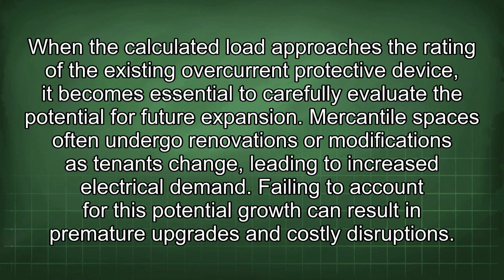When the calculated load approaches the rating of the existing overcurrent protective device, it becomes essential to carefully evaluate the potential for future expansion. Mercantile spaces often undergo renovations or modifications as tenants change, leading to increased electrical demand. Failing to account for this potential growth can result in premature upgrades and costly disruptions.